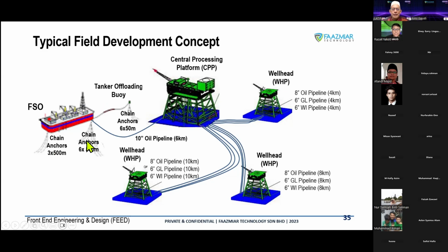And of course, the sizing of the PSO will depend on the production rate. So the production rate is 60,000, times 10 is 600,000, at least a minimum of 600,000 capacity based on the 10 days storage time or transit time. Okay, that's a typical development. We have multiple drilling platforms or drilling wellhead platforms, and then we have a subsurface platform, and then it will be linked to the storage, which is just for storage, because the facilities are there.